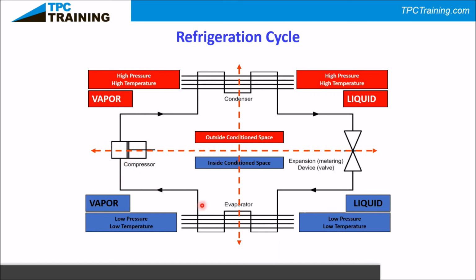Because there's too much liquid going back. Overcharged will also cause that, because then we're not going to have enough heat absorbed into our refrigerant in the evaporator to cause it to change into a vapor. So it's two scenarios we're going to see where you would get, I call it frostback. That's literally what it's called. Freezing of your evaporator coil.